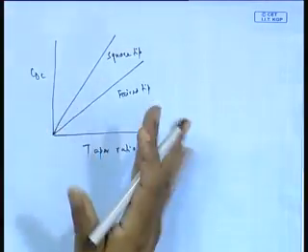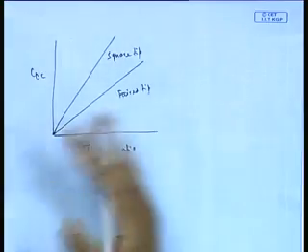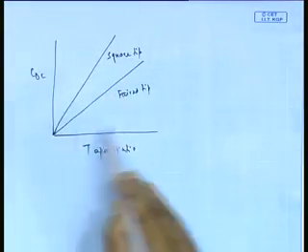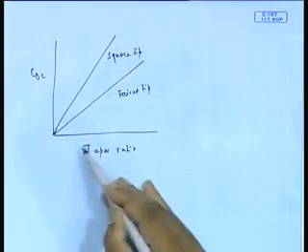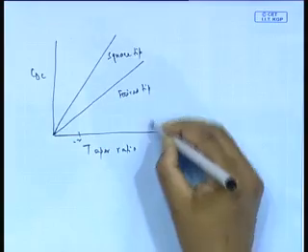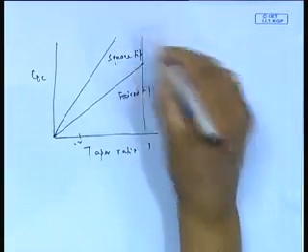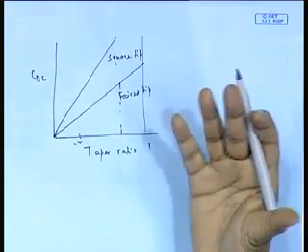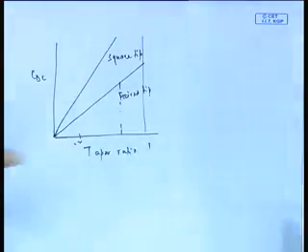I am not putting the numbers, you can see them in any standard textbook, but they seem to fit a linear variation with taper ratio. Taper ratio, for example, here this may be 0.2. It can go up to 1. It cannot go beyond 1. But for most ships' rudders the taper ratio is about 0.8, 0.9 in that order. So this is all like any empirical formula. If you have the graphs available, you can always apply that. Okay. Having said that, now let's see the other part.